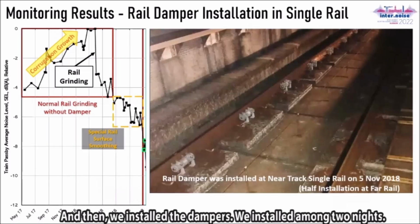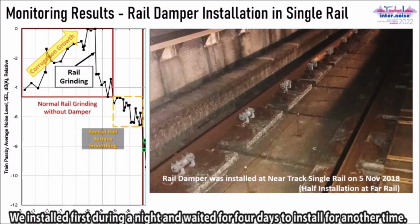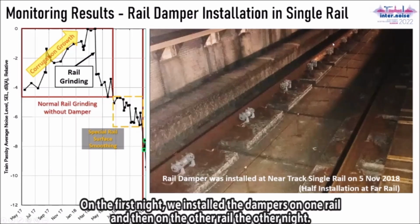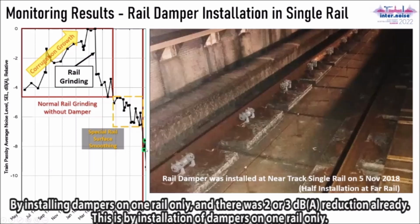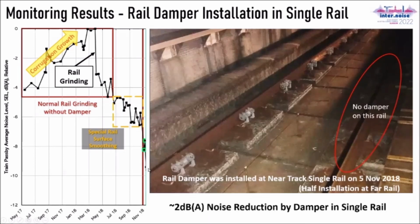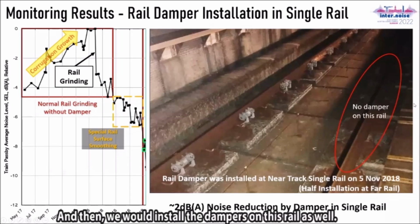Okay, then we install the damper. We install at 2 sites. Install first 1 site, then wait another 4 days, and then install another. So in the first site, we install the wheel damper on 1 wheel. Then we install another wheel. By installing on 1 wheel, it already has around 2 or 3 dB noise reduction. This is by installation of the damper on 1 wheel. There is no damper on this wheel. 2 dB reduction. And then we install the damper on this wheel as well.